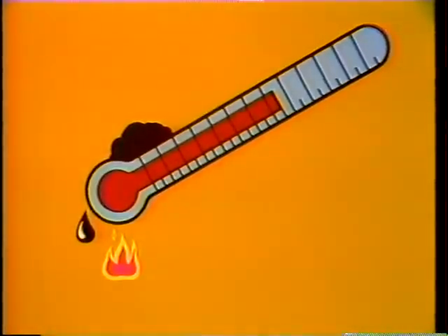Now, a grease's drop point is an important physical property because you don't want grease to liquefy while it's in use. If the operating temperature of an area is higher than the grease's drop point, the grease would tend to flow away from the area where it was needed for lubrication.